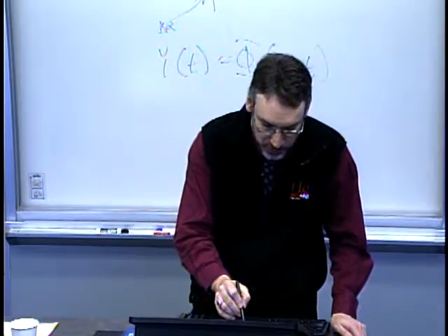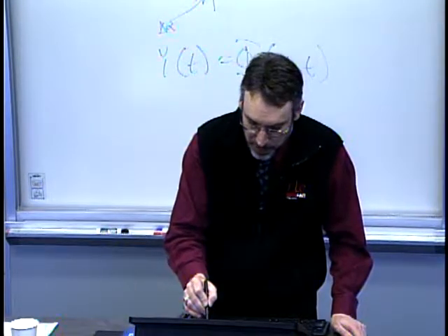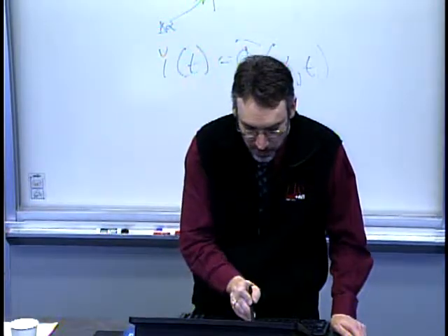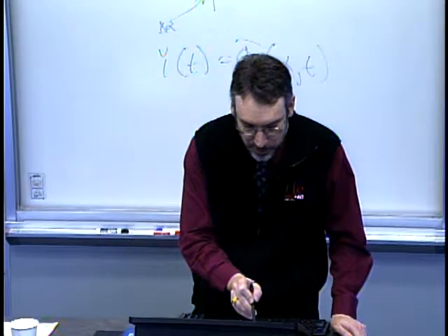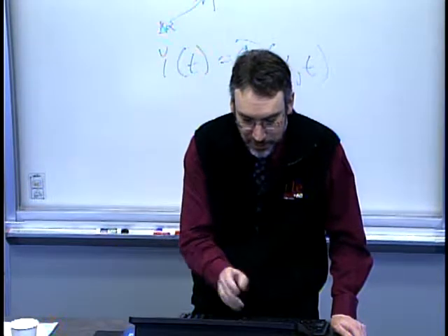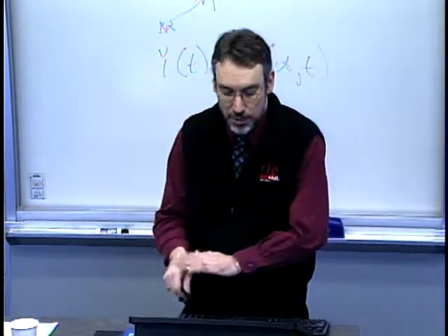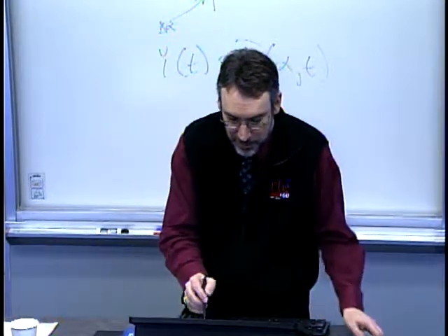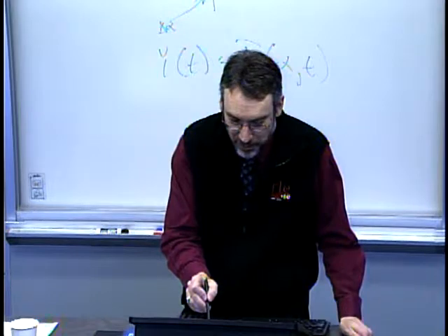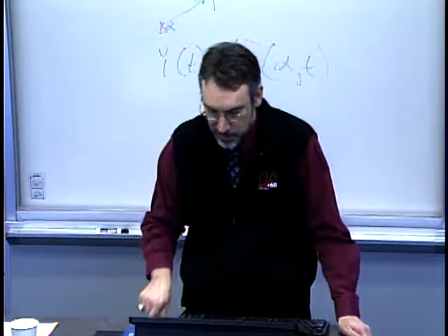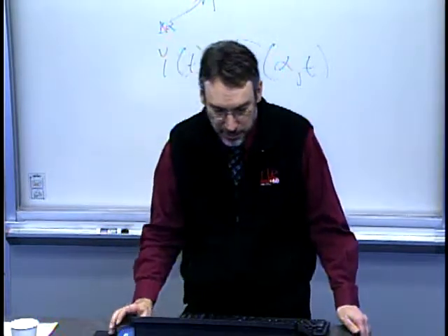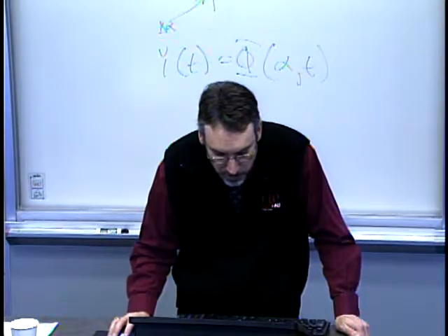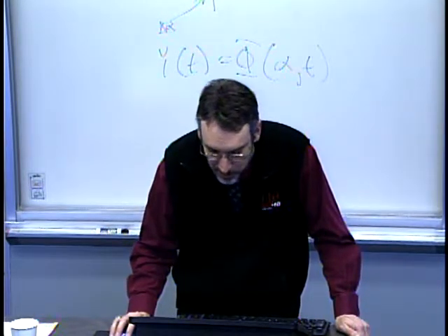And I'll just draw your attention here, there are clear intentional bands where this first segment says holding time was 5 seconds, injection pressure 40%, and we're changing here. This is a holding time of 10 seconds. Here's another holding time of 5 seconds and 60%, and whatever's lurking under there, I think it's a holding time of 10 seconds.